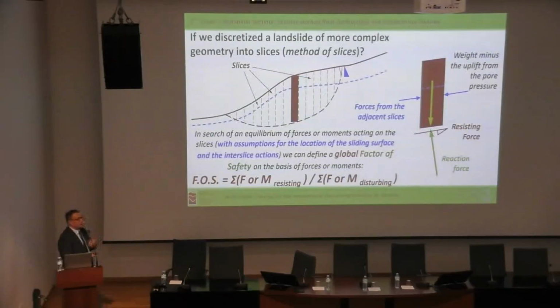So this discussion about partial factors and total factors when it comes to landslide analysis and slope stability is not just a matter of comparing numbers. It's a matter of comparing estimated sliding blocks, and the partial factor method can very easily lead us to a very misleading location of a sliding surface, which itself will then lead us to a misleading selection of stabilization measures.